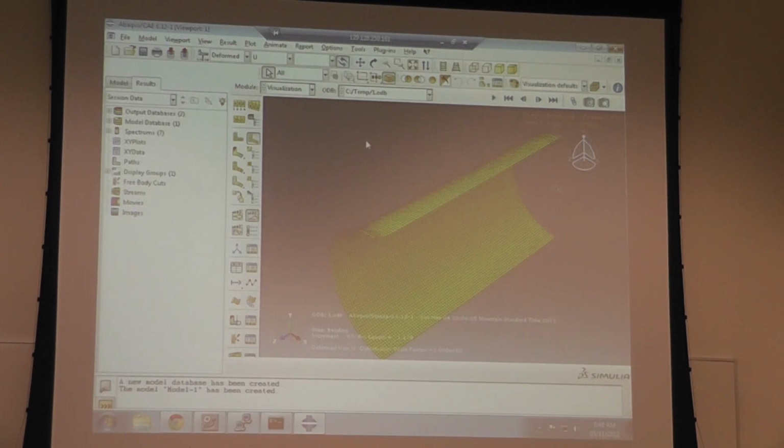Okay, so how can I model something like this? Since I'm showing you the results, what I'm interested in is what is the load and what is the rotation at this node. So I don't know the load. I apply a load of, I don't remember, let's say 10 to the power 9. But this 10 to the power 9 is not the actual load of the structure. The actual load of the structure is the load proportionality factor multiplied by that load. So the load proportionality factor is a history output.